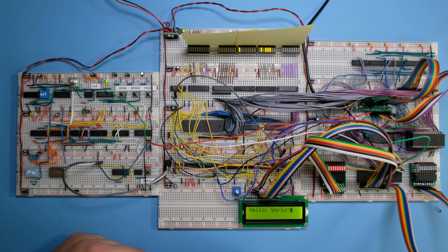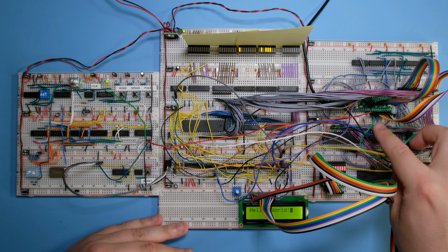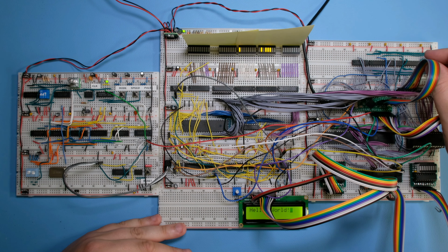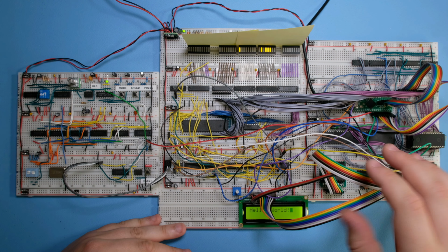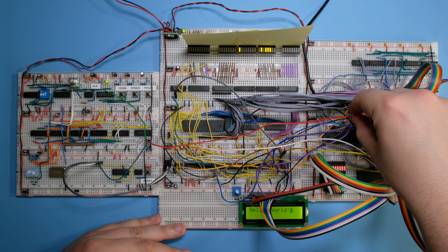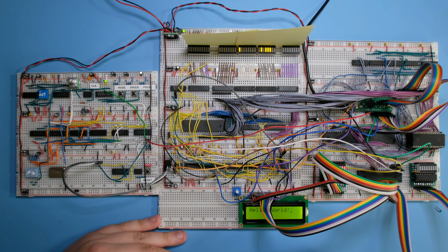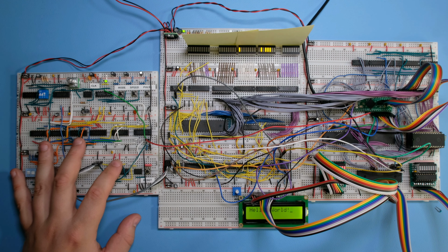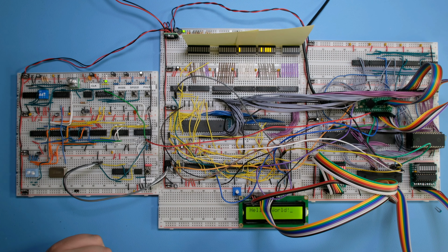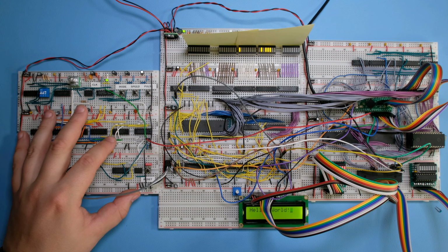Okay, so I'm pretty pleased with the progress that we made in this video. We did a bunch of work on the Teensy monitor. We've added this new header so that we can access new GPIO pins. And we made the first use of these new GPIO pins by controlling the clock output from the Teensy and being able to enable and disable the built-in clock when the Teensy is driving the CPU, and we're monitoring it through the serial monitor. Then we put some finishing touches on the clock.